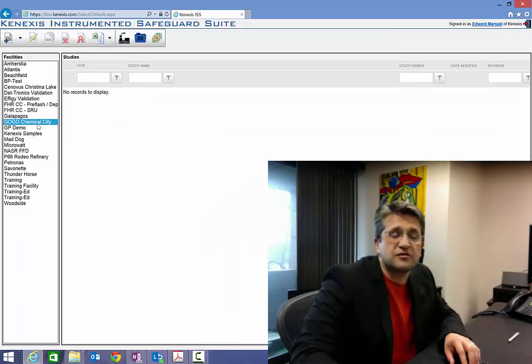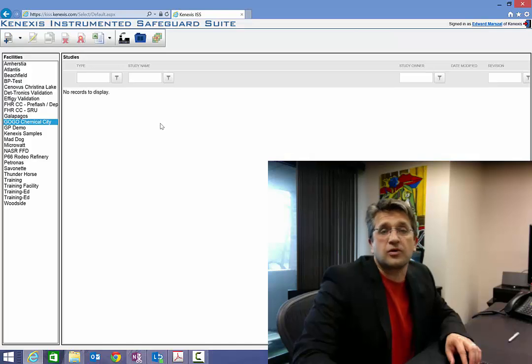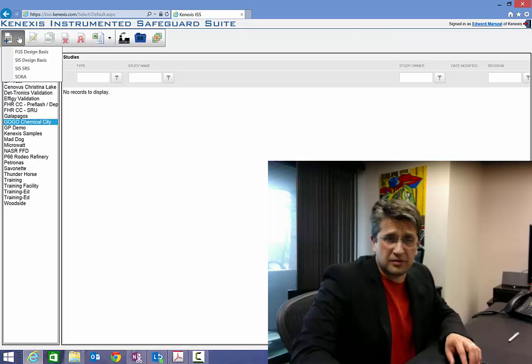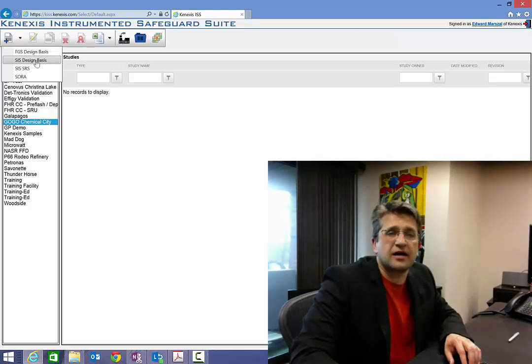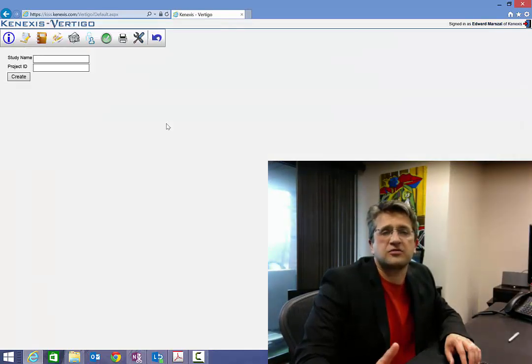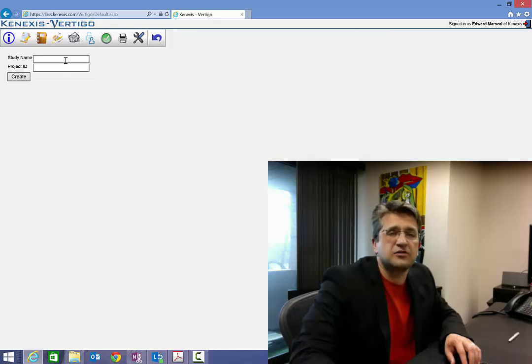I select that in the facility list, and you'll see that there are no studies. Since I just created the facility, that would make sense. So I'm going to need to add a new one, and I do that by clicking on the Add Study button in the action ribbon. The type of study that I want to create is a Vertigo study, which is an SIS design basis, as opposed to an FGS design basis, fire and gas. That would be for Effigy. So I click on SIS design basis, and it begins the process of creating a new study.